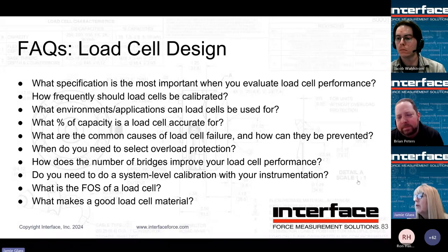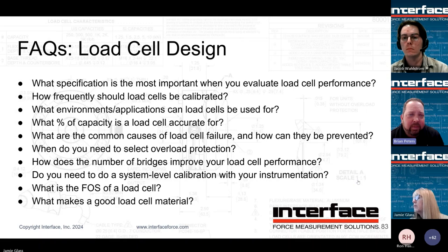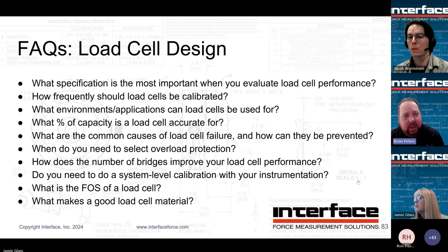Another question is, how do you overcome crosstalk for multi-channel load cells? Good question. You try to optimize through the flexure design. There are going to be limitations, of course, and it comes down to which is your primary axis of measurement. If you're talking an axial-torsional cell, and your axial load is much more important, then we would want to go with one of our 1216 models, which starts as an LP axial load cell and adds torsional bridges.